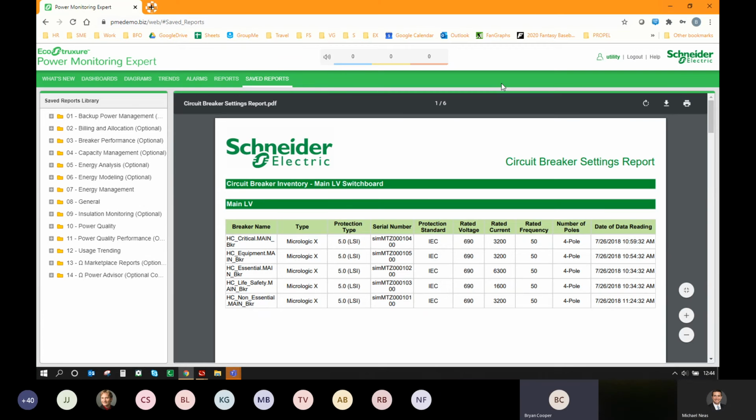Okay, thank you. And that's, I think, kind of how we're set up. My only concern, at least with our system, is the lag. We have multiple meters, and say a single meter triggers. We don't see that email for about 8 minutes. If it's a more system-wide event that triggers lots of meters, that first email usually doesn't hit us until the 1.5 to 2 hour mark after the event. I wasn't sure if it was something internal to our system or if there's something we could do better in the software.